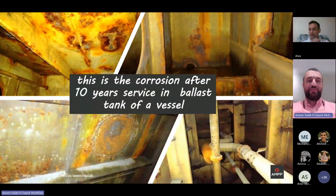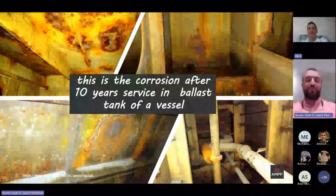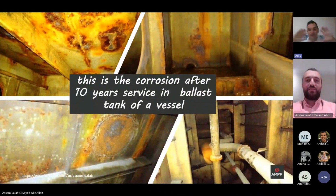So you are not willing to call it wet blasting. No, we would say high pressure washing. It's 500 kilograms. Washing, yes. It will not remove the rust itself, but only remove the loosened paint, the paint which is badly adhered, and then they repaint with 2 coats. It's not very effective, because in the next photos, if you slide, Asim, please slide to the next photos.